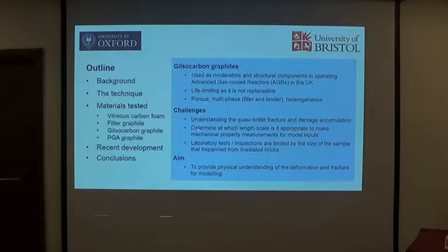Well, you can see that I listed 4 different types of materials here. One is the carbon, and the other 3 are graphites. And these 2, carbon and PGE graphite, are the graphites that are used in the UK nuclear reactors. In particular, graphite is used as a moderator and a structural component in the currently operating advanced gas-cooled reactors in the UK. That is providing about 15% of the electricity to the UK nationals at the moment.